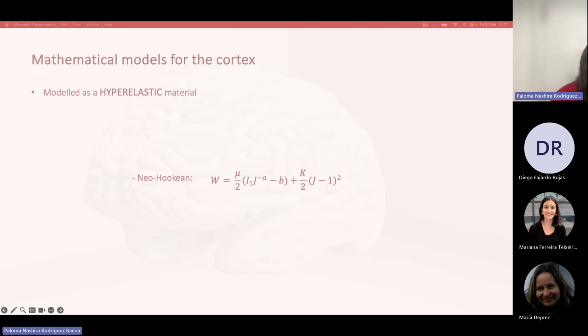That wouldn't be the Neo-Hookean model. That would be another model. So then you only need I1. If you're using Neo-Hookean models, yes, but the constitutive architecture is a generalization of all of the models. So by choosing to use more or fewer invariants, you could be constructing the other models. Sounds straightforward enough then.